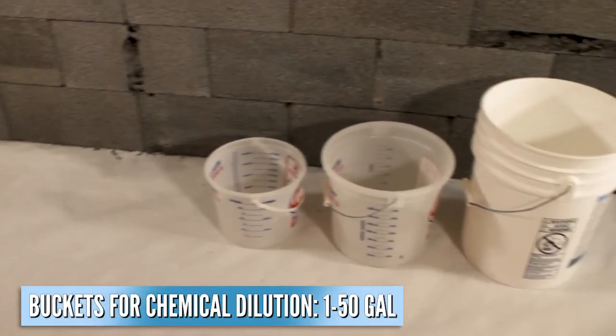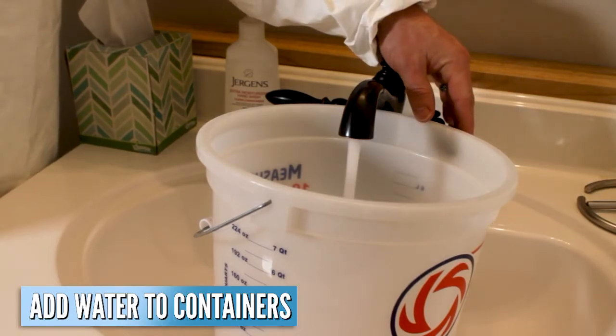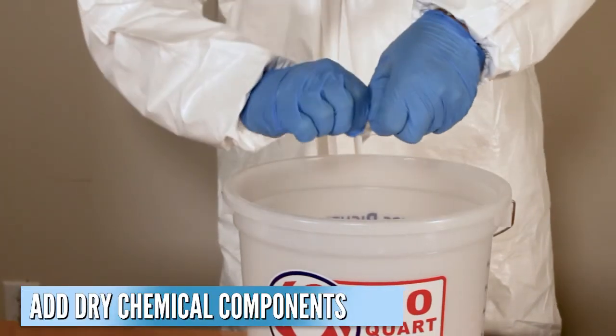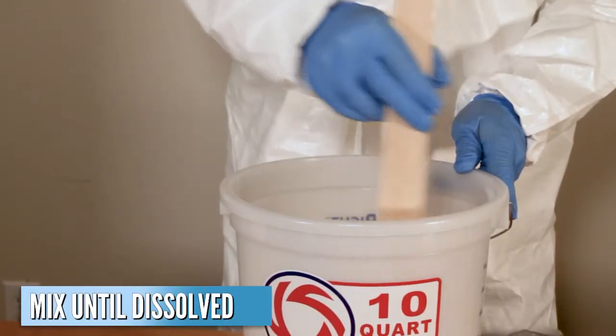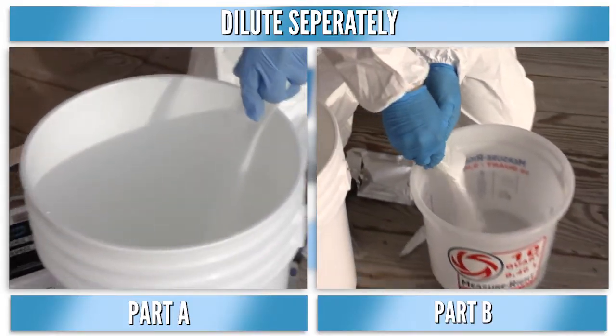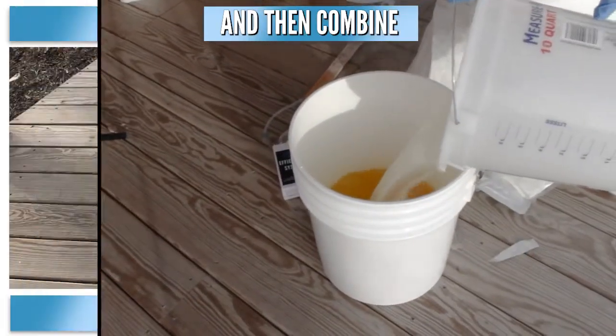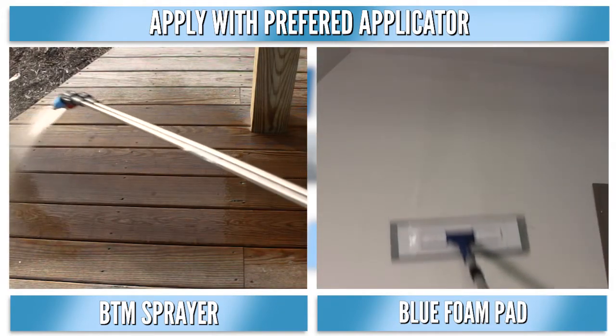Begin with clean mixed containers. Add water into each container prior to the chemical. Add the dry chlorine dioxide chemical components to the water and gently mix until nearly dissolved. When working with two-part kits, dilute each part individually before combining. Apply the chlorine dioxide solution to the surface with the preferred applicator.